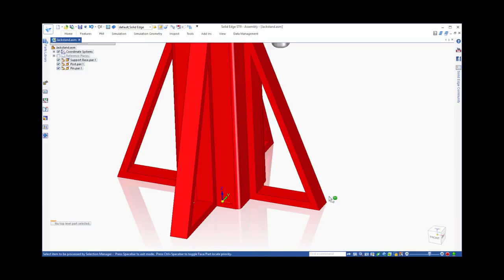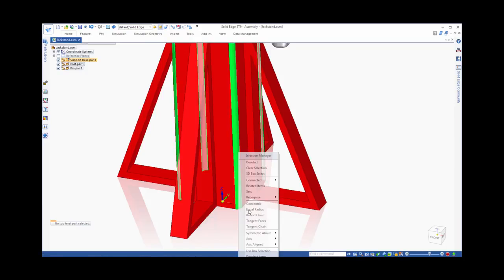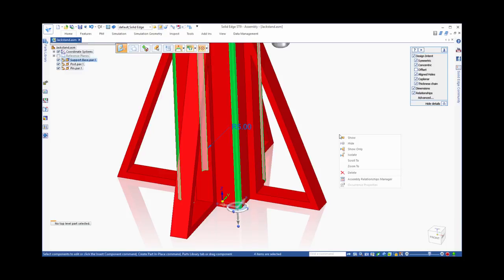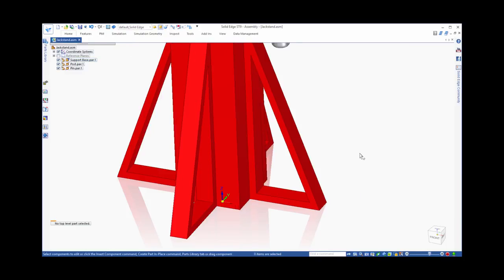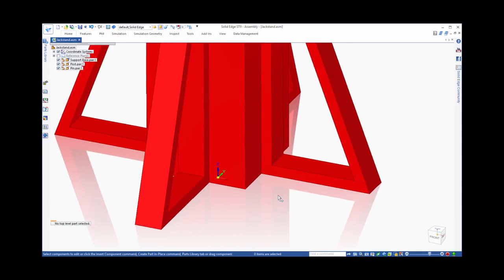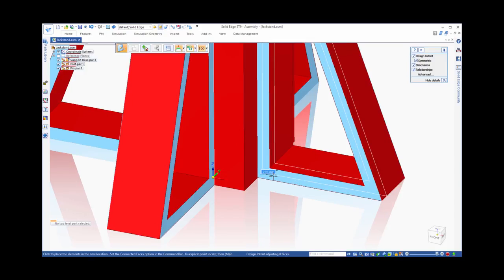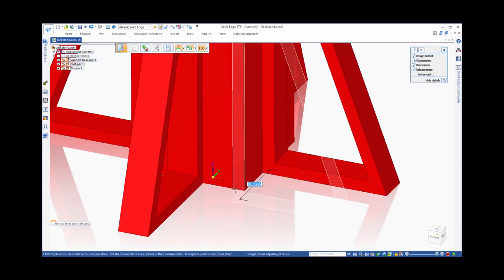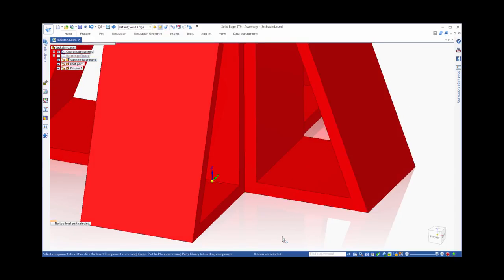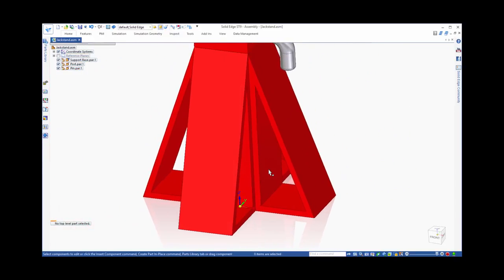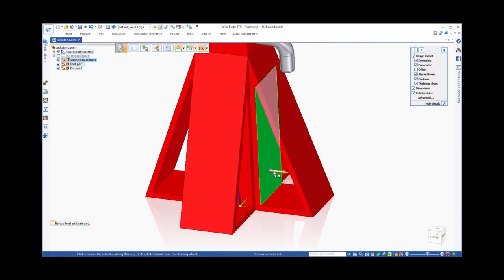The Selection Manager tool enables us to interrogate the model automatically to detect and find all the rounded corners that contain the same radius, and in this case we'll use the selection to remove these rounds. Synchronous technology maintains symmetry in the model by recognizing another design intent relationship as we drag the face to the corner of the rectangular section. Note that all the sides are also updated to reflect the same change due to design intent and patterning.